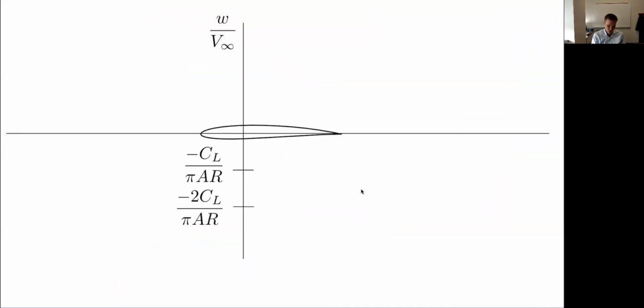So what we've seen so far is that we've had the simple model, and actually we made it a little more complicated, but I'm just going to draw with one horseshoe vortex for now. We took this wing, put a horseshoe vortex on it, and actually we extended it so that there's an infinite number, but let's just draw that for now. It's the same idea. So we've got trailing vortices and a bound vortex. Actually, we will consider all of them because that's what we've done. So we've got all these trailing vortices, an infinite number of them.